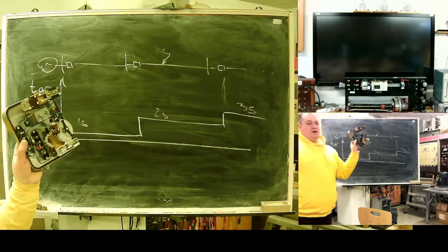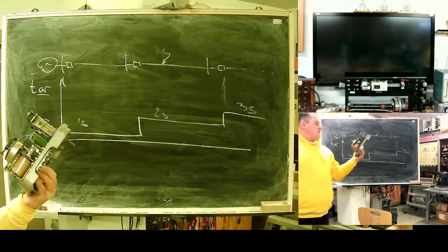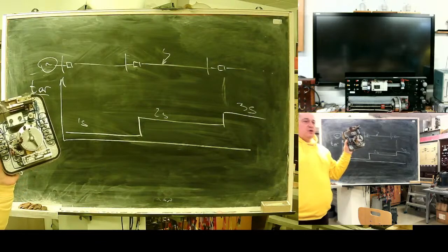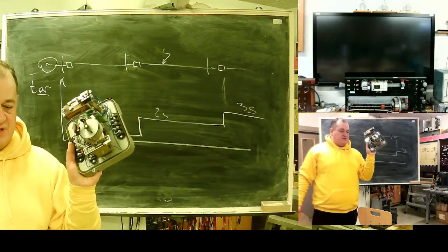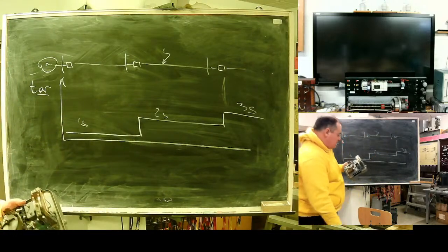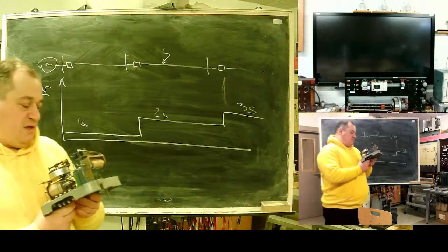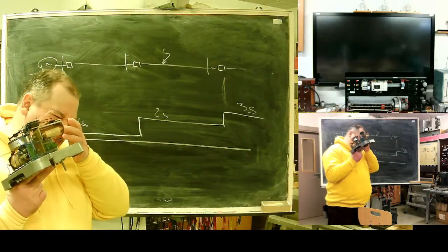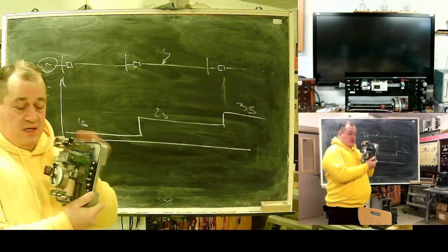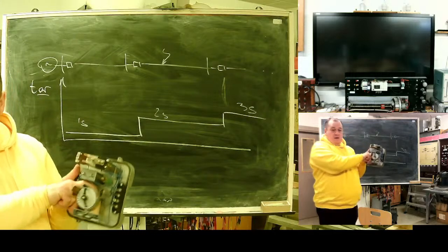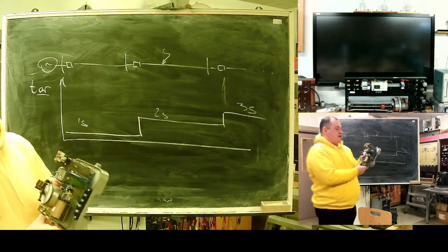This one is an old school reclosing relay. As I understand, the 1958 model, some still in operation. Very successful design. Relatively inexpensive, extremely robust, and what was good, it's very fault tolerant. What does it have inside? Clockwork to set the delay before reconnection.